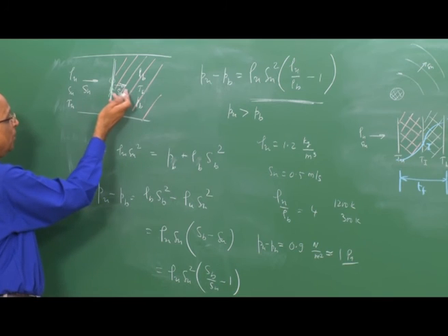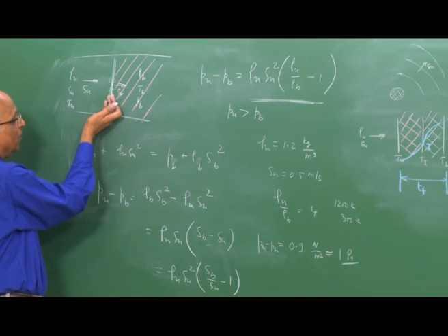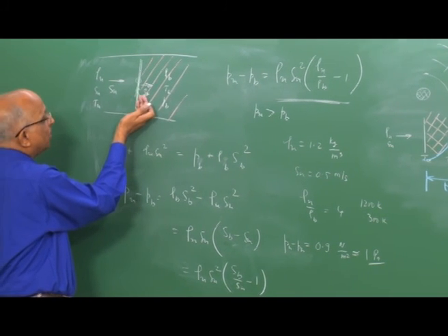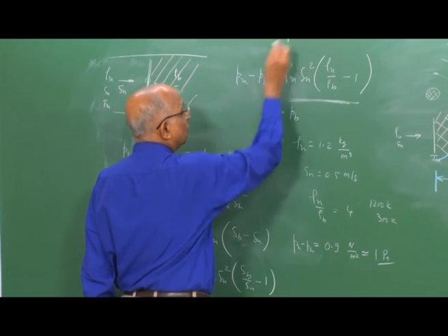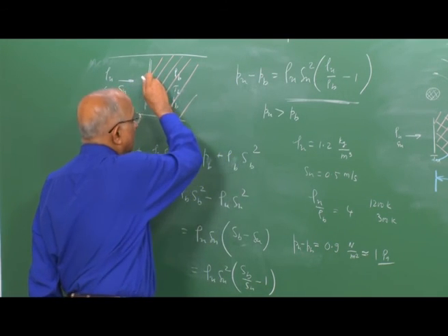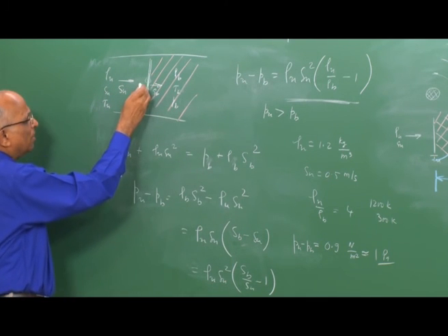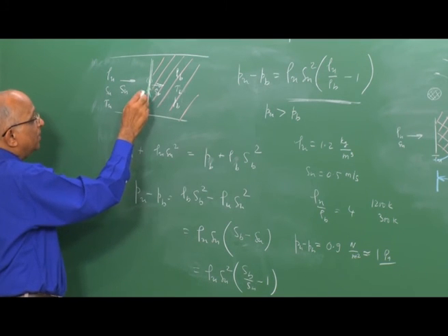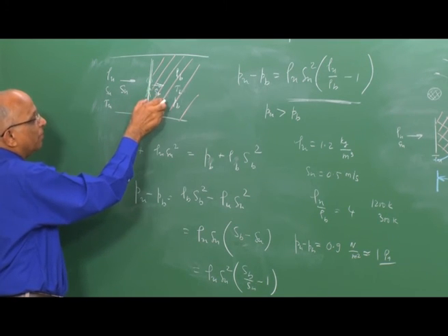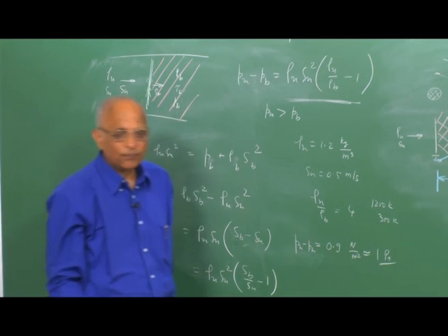pressure, the fall in pressure is very small, and therefore, whenever we talk in terms of a combustion front, we talk in terms of a constant pressure process, and that is why we are justified in using the value of Cp while determining the flow properties over here. That means, across a combustion front there is hardly any change in pressure, but mind you, let us keep this clear, there is a drop in pressure and this drop in pressure is somewhat small.